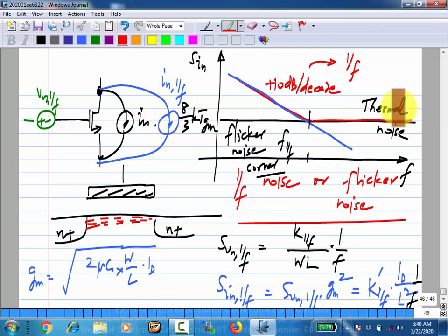Yes? They are not different for our type of first order calculations, but the flicker noise may be lower in that way. So far as I know, they are the same. All the differences come in the engineering. You cannot have arbitrary widths because of the fin and things like that. And it just turns out that you will have better gm/gds and so on. But those are parameter differences, while the model itself, I don't know if there is a difference.